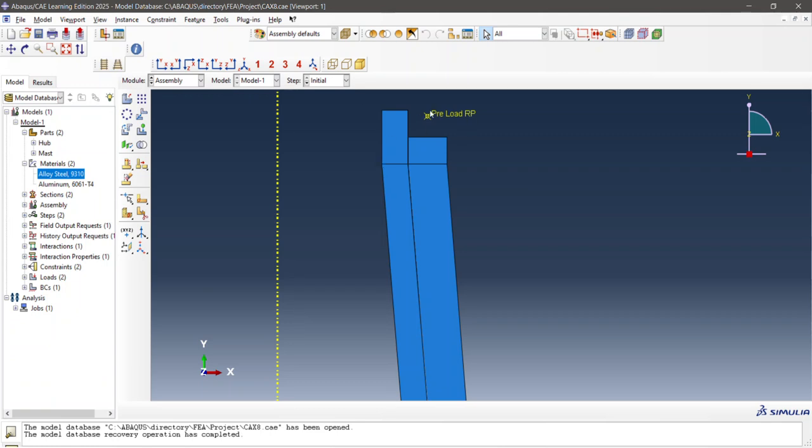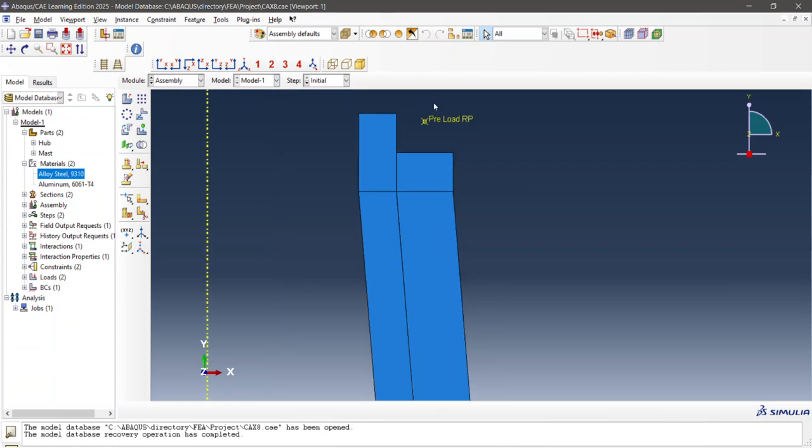Now the bolt is about 3/8 inch in diameter, and it gets torqued to roughly 22 foot-pounds per bolt. So there's 12 of them total. Now I'm working in metric. Backing that out, how I did this is I took the torque equation and solved for the compressive force needed to achieve that torque.